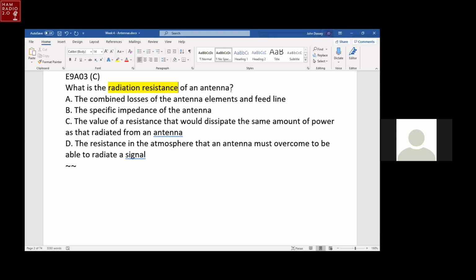But of course, with everything, there's a point of diminishing returns. If you get more than 15 or 20 radials, you're not going to help it if you go to 50. 15 or 20 is a common number of radials that can be used. If you have 3 radials, it'll be way better to have 9 or 10 or 12.